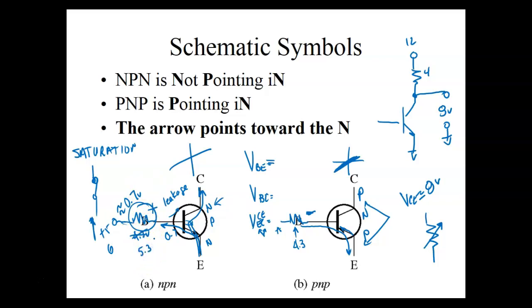The resistor's fixed, right? You understand? If the voltage goes up, then what's got to happen? The current's got to go up. If the current goes up, that's controlling the base current, so base current goes up. If the base current goes up, then the valve turns on more.